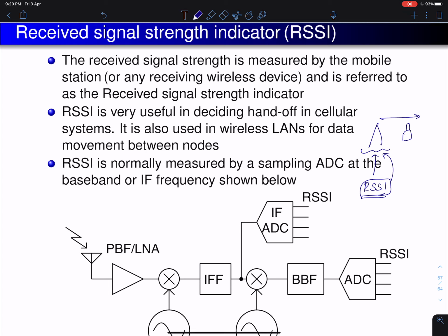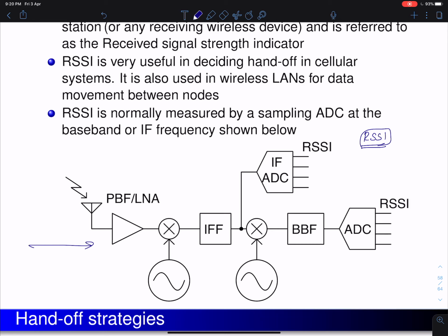Now what I have shown here is a typical receiver of a base station with an ADC. The receiver architecture will look essentially like this. So your signal is first received by a block known as an amplifier, which will just amplify the signal because your received signal power will be very low for the circuits to process it. So first you have to do amplification.